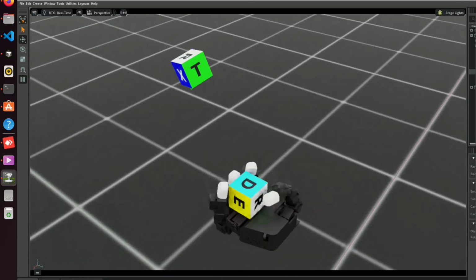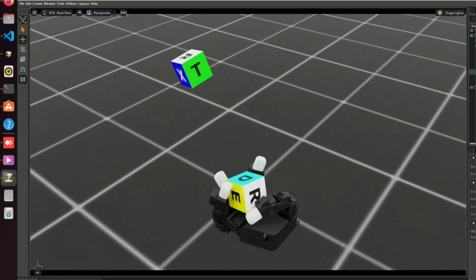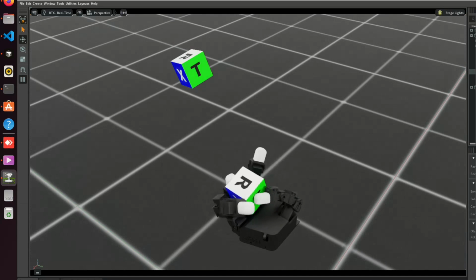Robust 3D reorientation also needs more work. The current error metric, geodesic quaternion distance, may not be optimal. The policy does often reach the goal pose, but sometimes doesn't make progress at all. Alternative trajectory planning methods could be computationally intense, but more efficient for training and deployment.